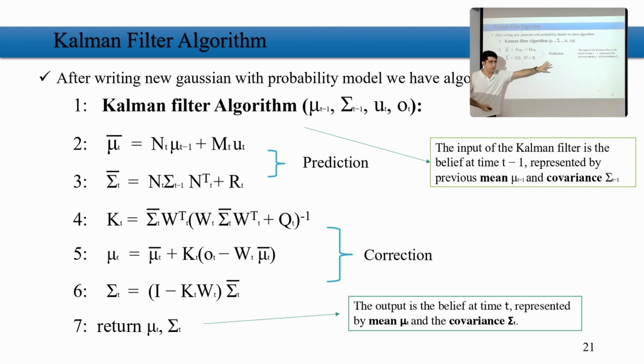So what we've done, we first calculated the prediction. The prediction gave the predicted mean and predicted covariance. So this predicted mean and predicted covariance come from where the initial robot was, what the control command was that I've had, and what the observation is. Observation will be used here. For now, the control command we've used. And we've used the matrices, linear matrices, to update the mean and covariance. I'm not going to, again, explain that in great detail. Last week we did it.